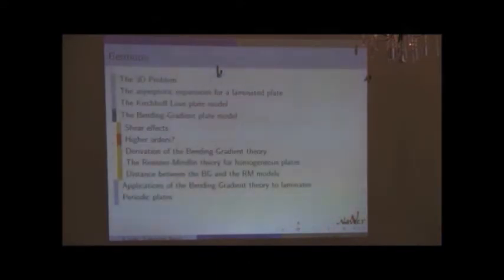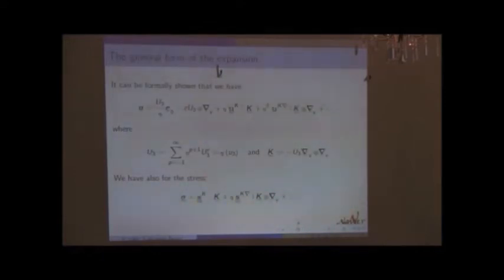So, okay. We played the game. We can go to any order you want, higher and higher. And it's an endless game. In the presentation I derived the leading order displacement, the rotation, the transverse Poisson effect related to the curvature, and we just discussed the in-plane warping related to the gradient of the curvature.